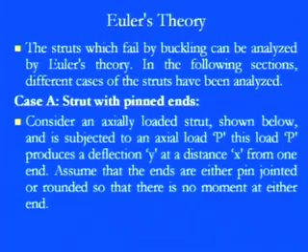Once we know the member and the conditions it is under, we can easily establish the limiting conditions, saying this is before the buckling load and this is the buckling state. In that category, in the Euler theory, we have taken the first case as the strut with pinned ends. That means it is like a simply supported beam.